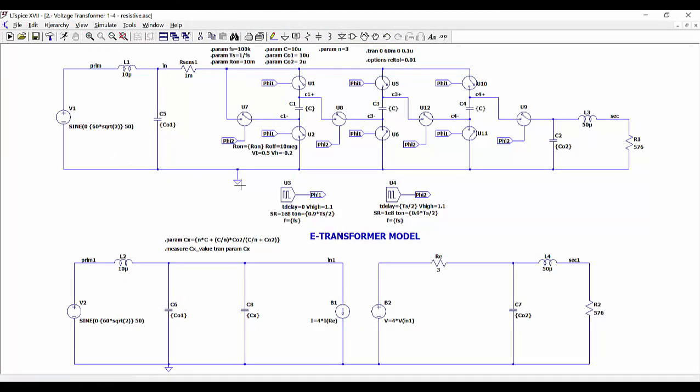On the top we have the full converter with all the elements that we have just obtained. And here at the bottom we can see the equivalent circuit, the model of our transformer, also to check that it is going to behave as the actual circuit. So now we are applying here at the input on both circuits the input voltage with 60 volts RMS. This is the peak value, 50 Hertz.